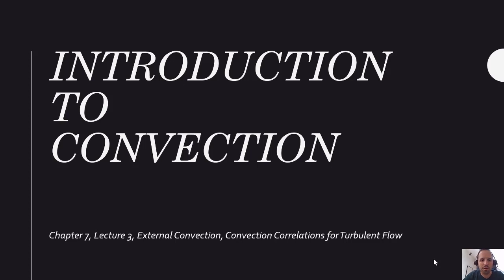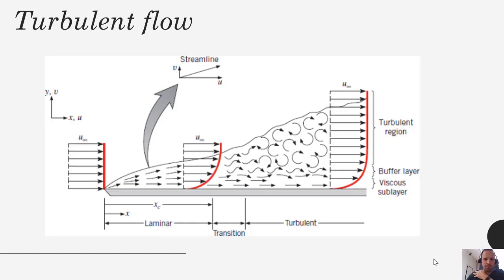we didn't really solve it, we were able to observe the solution for laminar flow over a flat plate, and getting to that solution required simultaneously solving the energy balance and the momentum balance and the continuity equation, which are all PDEs, so it's three coupled PDEs, and that made for some fairly complex math. So that was for the laminar region.